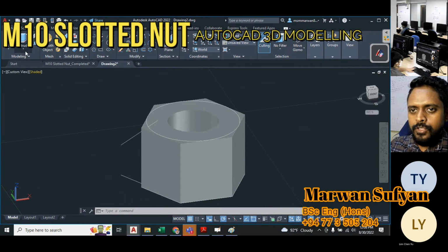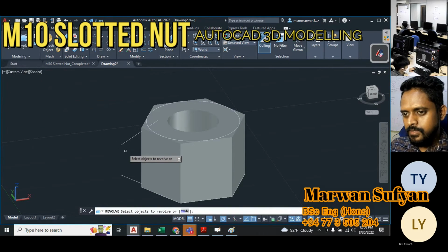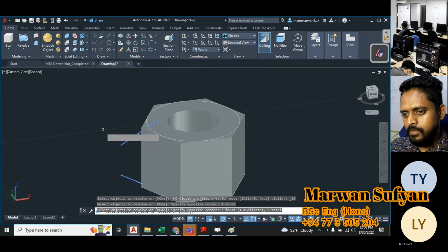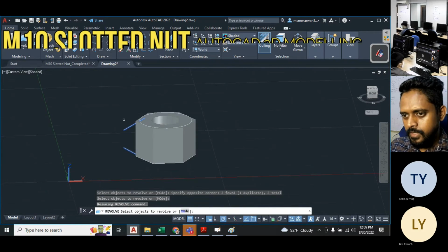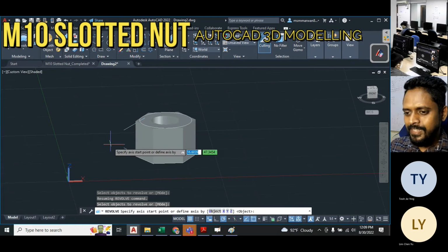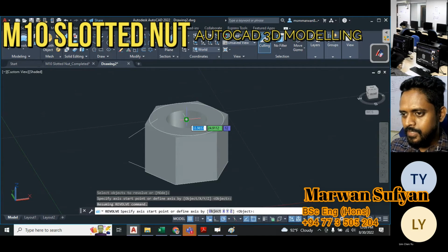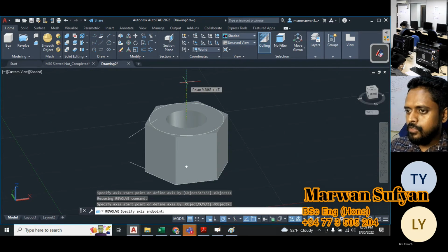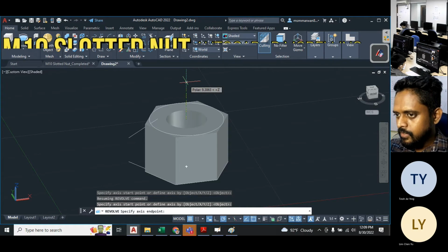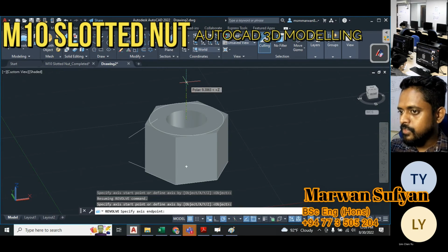I'm going to use the revolve tool, and I'll select this line and also this line. Both lines, I selected 2 lines. So select revolve, select 2 lines and hit enter. Then it says specify the axis of rotation. So in order to select the axis of rotation, I'll select this center. Then I'll move down or else move up. You can find my line is going along the Z axis. Now see what is written: polar 9.3863 angle, and you have a Z mark. Now the very important thing is Z.